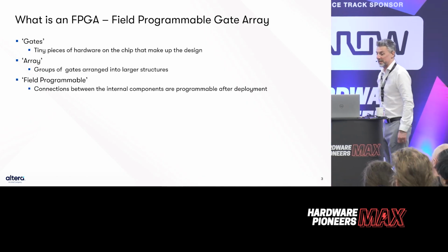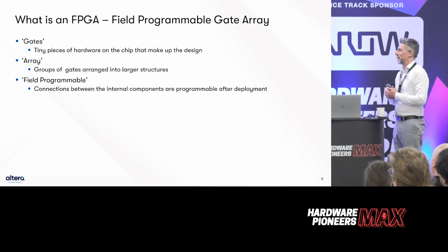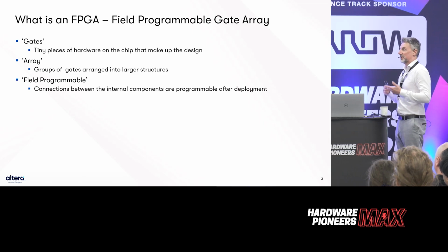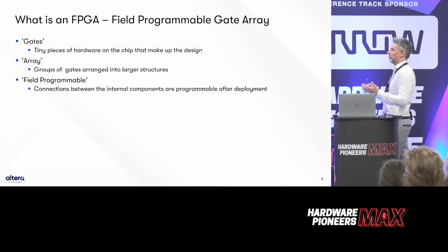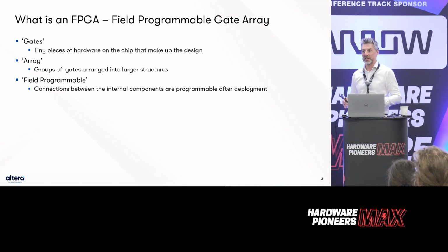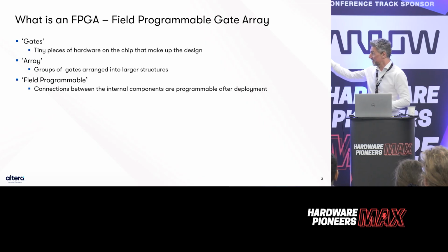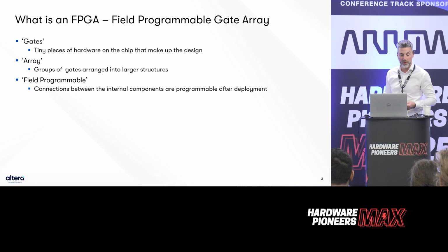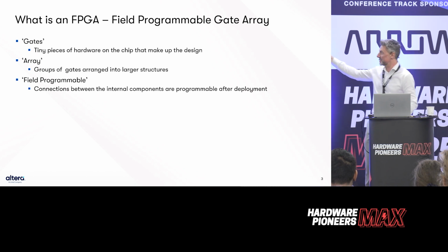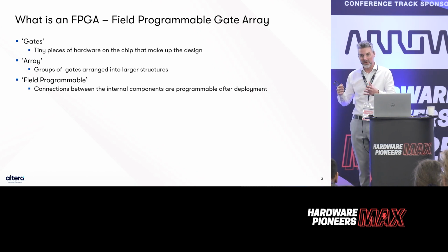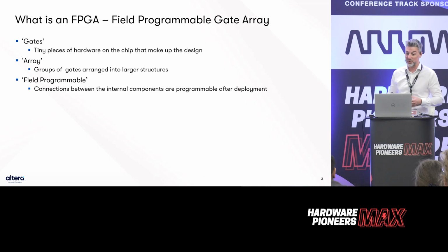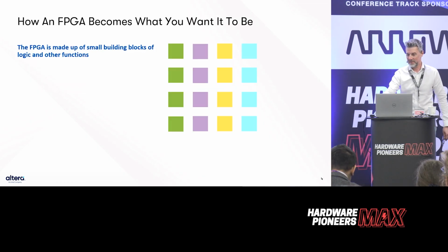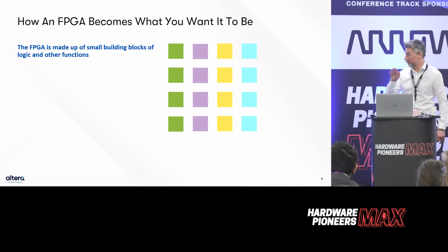All right, what's an FPGA? So it is a field programmable gate array. So basically, it's a piece of flexible hardware you can create your own algorithms implementation out of. It's built up in a certain way, so gates being the kind of lowest level building blocks you use. These are then created together in an array to create some sort of function, some logic function you want to implement, and then they're all connected together inside the device.